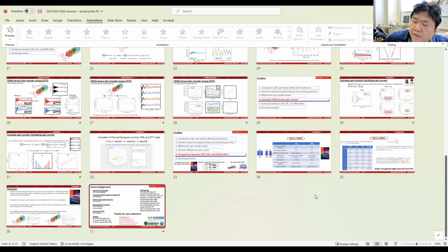Yeah. But what about the thickness dependence then? Well, it's a very good question. We haven't studied the thickness dependence very thoroughly, because in order to have very high quality perovskite materials, we usually use the solar cell recipe, right? So it always gives you the best morphology at a certain thickness. If we reduce the thickness, the quality is bad, the morphology is bad. So usually all the samples we got are around 100 to 150 nanometers. That's the optimized domain for the chiral hybrid perovskite. But studying thickness dependence for solution-processed materials is very difficult. Yeah. I see. Thanks.